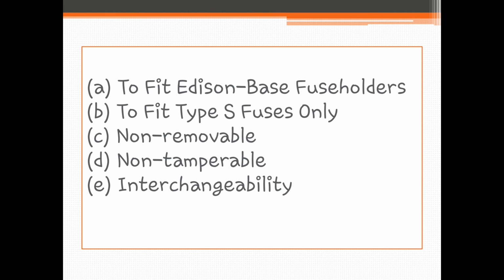Non-tamperable. Type S fuses, fuse holders, and adapters shall be designed so that tampering or shunting, bridging would be difficult. So, gubo na lang jud siya. Interchangeability. Dimensions of type S fuses, fuse holders, and adapters shall be standardized to permit interchangeability, regardless of the manufacturer.